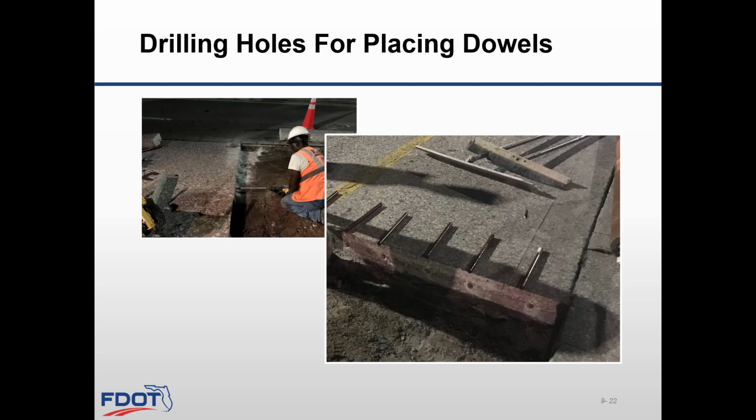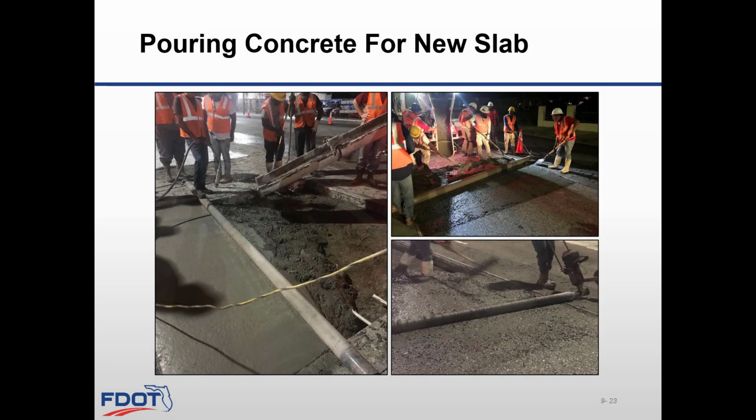Contractor always should keep spare emergency slabs to place in case the slab being removed breaks into pieces. Before pouring a new slab, ensure the base has not been disturbed by the removal of the broken slab. Concrete is poured, then vibrated and rolled for a smooth surface. As mentioned before, the slab needs to achieve at least 1600 psi before placing traffic back onto the new poured slab.